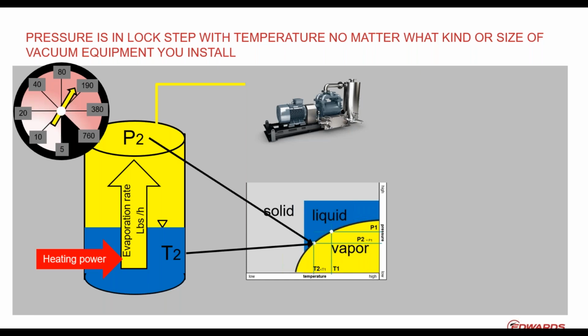your vacuum that you apply, if it would be too small, which means it is less ACFM than the heating power generated in pounds per hour, you would overheat your product. The temperature T2 would go up, which, since everybody in this industry wants to avoid that, is deteriorating eventually the product. There's a reason why you want to have a temperature at a certain range in the liquid. That is the one thing.